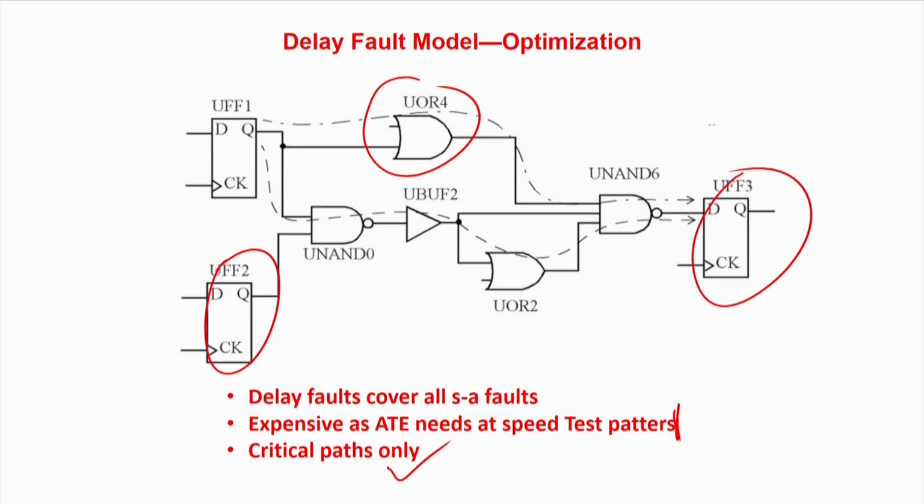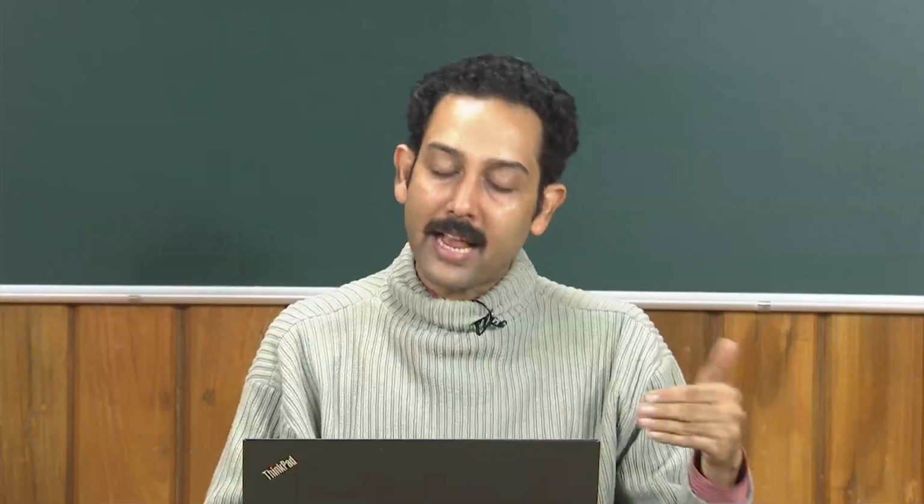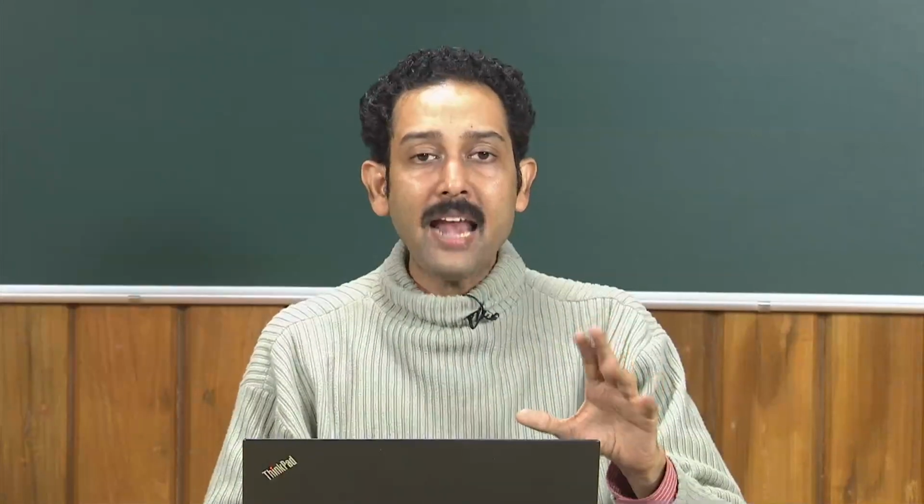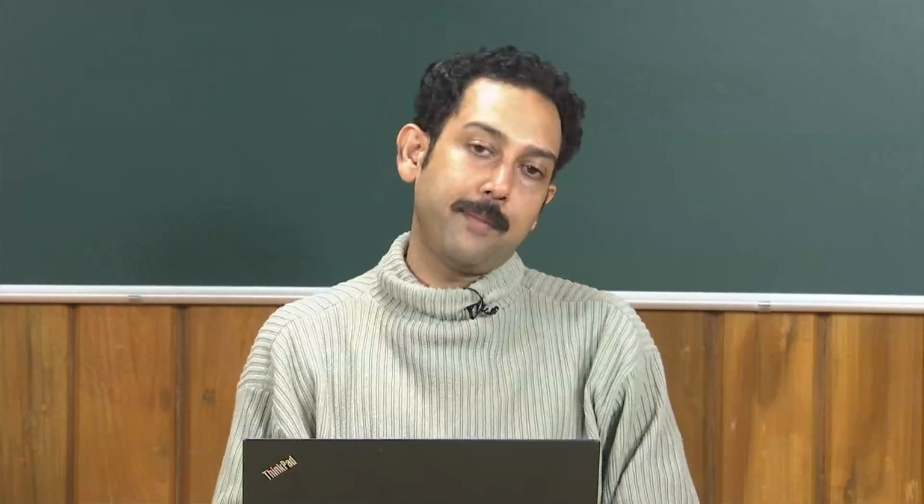So what have we seen in this? We have basically seen that advanced fault models are very much required if you are going for testing of circuits at the deep submicron level, which is the de facto standard of fabrication for NoCs and SoCs. Interestingly, if you go for testing of the advanced fault models, automatically some stuck-at faults will be tested. What remains to be done, you go for at a later phase, so that you get 100% coverage.